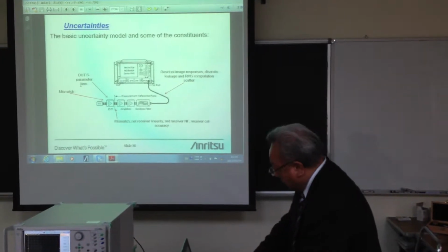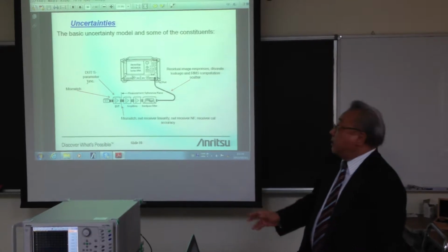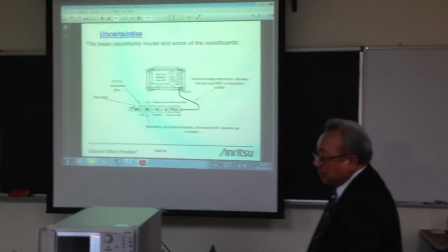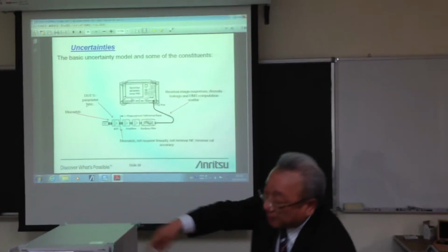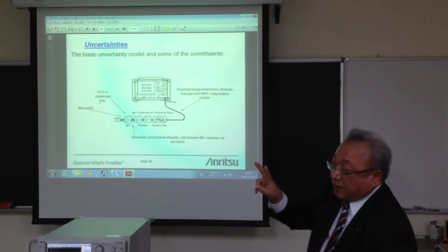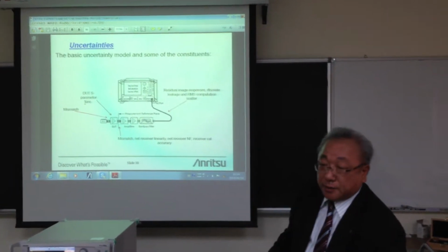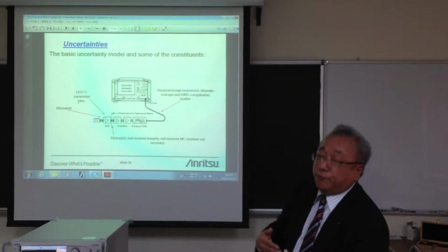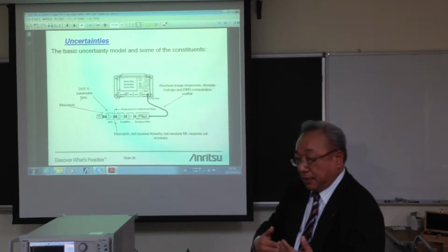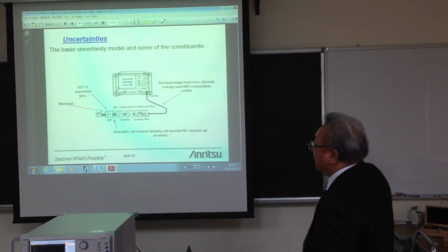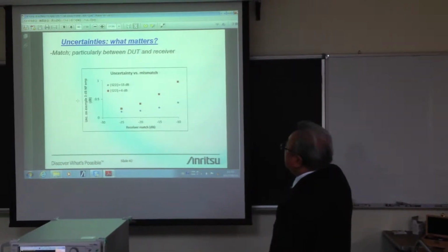And the measurement procedure is the same as the standard coaxial systems. I need an external composite receiver here. Now it is constructed with two pre-amplifiers and one bandpass filter. And now we are adding an isolator to improve the impedance mismatch of the composite receiver. This is something like that.